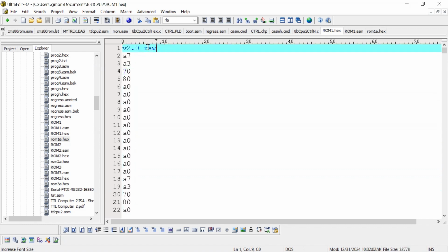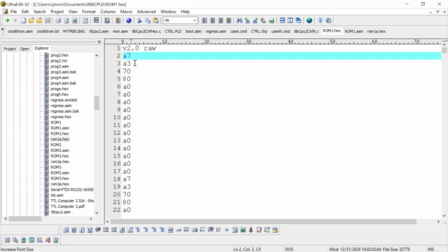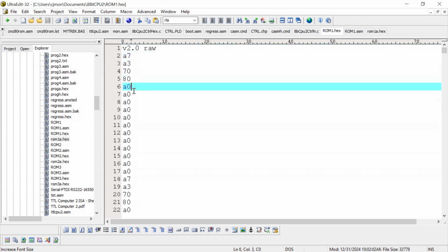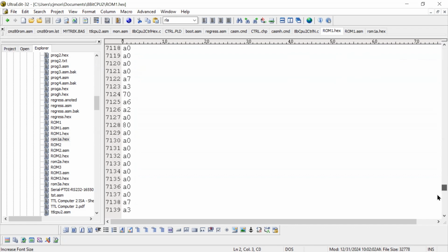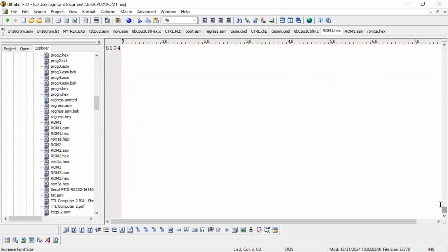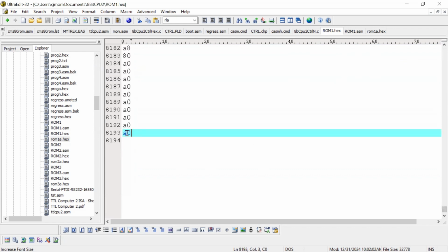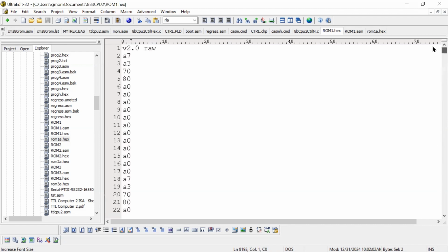And you can see it's just a little bit of a header, and then each line just has one hex byte for the ROM, right? That starts from byte 0 and goes all the way down to byte 8192, which is here. So all 8K bytes are there. So that's what the file looks like that the microcode program generator is producing. And I modified that. Well, it was a simple change.